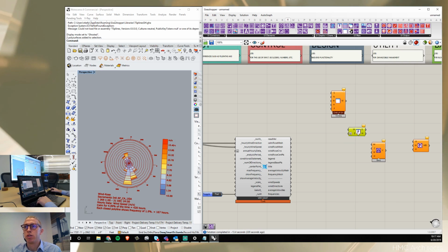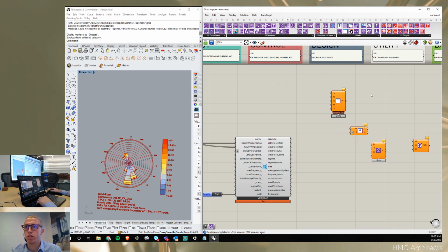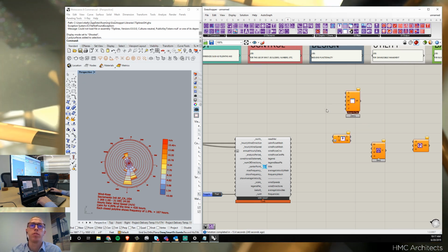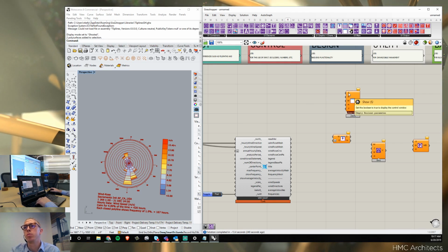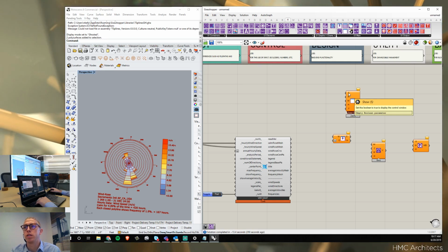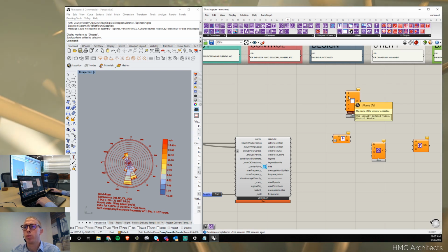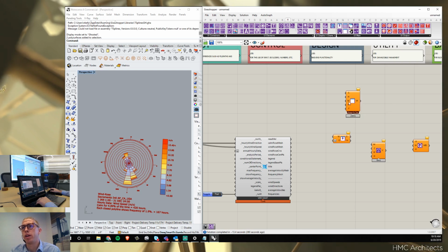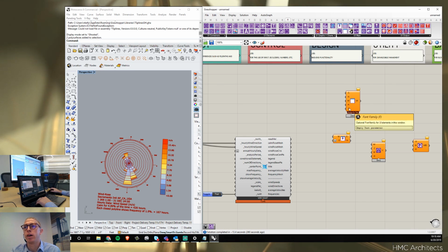And that's going to be a child of the Grasshopper window. Or we could just say always on top, which is also not a bad choice. It's always going to remain on top of both of these programs. So a few things that we need: a Boolean toggle, so that we can set it to true to show the window. And I think that's the only one we need for this component to run. We can change the name, the width, the height, and then the font family.